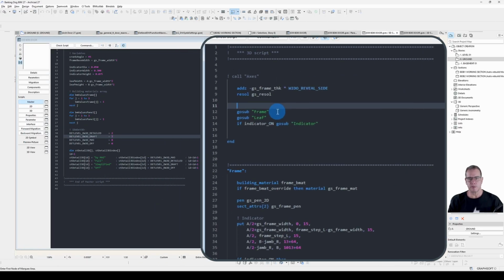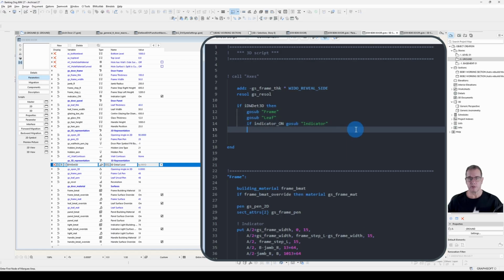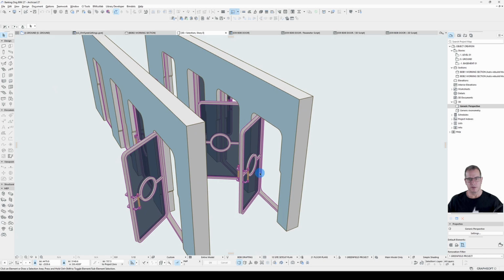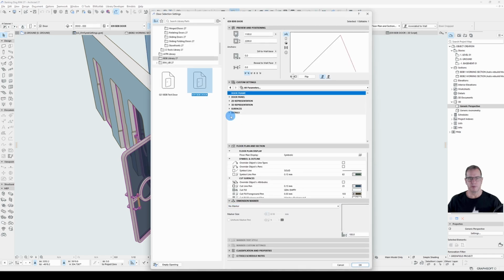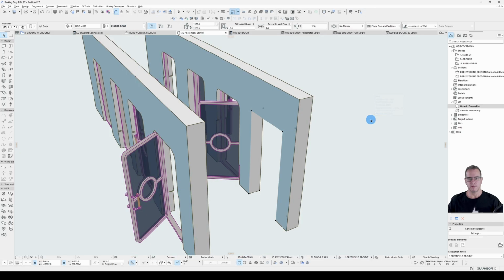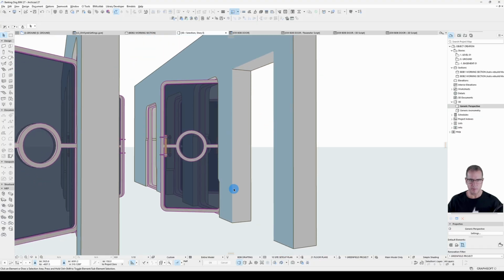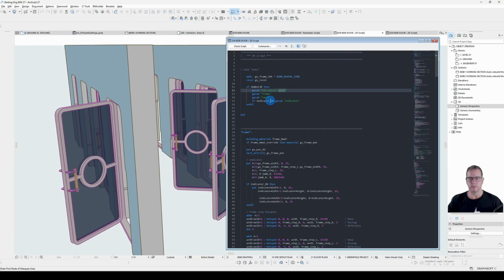And here we've got a simple if statement. So if det level is anything but off, so if it's true, and true is anything above 0, or anything not 0, we can do all that. We'll check that. So I can easily check that. Let's have a look at this one. 3D, detail level, off. Right, that's pretty easy. Now I may want to refine that a little bit to ensure I still get my opening lines, but that's the basics of it.